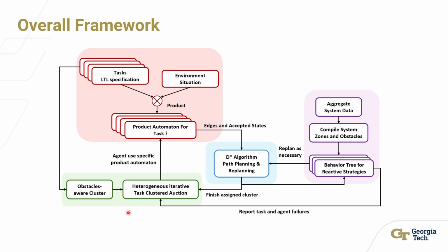For the path planning algorithm, we apply the D-star algorithm, which is well suited to dynamic environments. Unlike traditional approaches that rely on grid-based maps, we are using an adaptive Halton sequence to generate the planning space. I will talk in detail about this component in the upcoming slides.